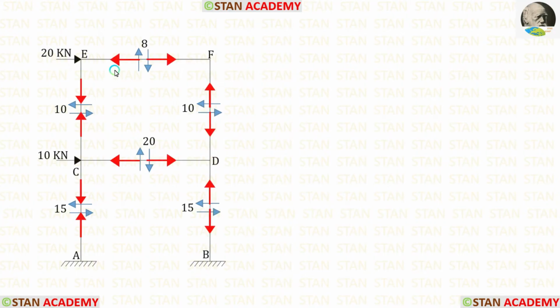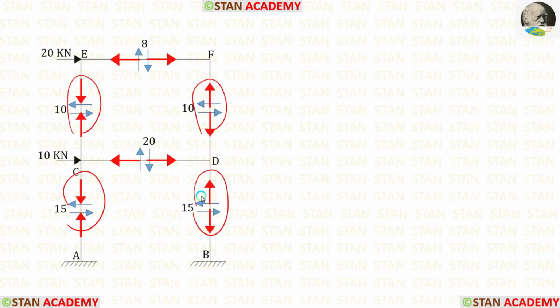The axial forces in the beams will be compressive. In both of the stories, in the left column, let us assume that the axial force is tensile, and in the right side column, it is compressive. If we get any negative value, we can change the direction later.